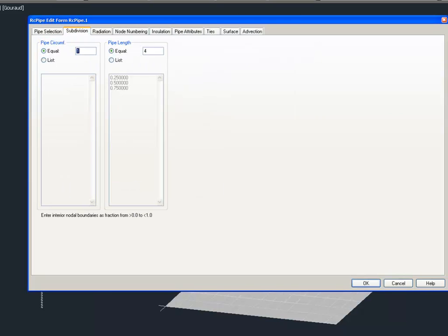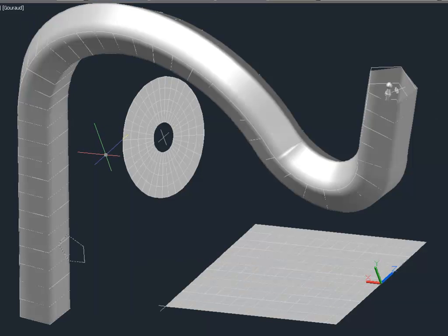And to make things a little bit more visible, I'm just going to put in about a cross-section of 40. Or excuse me, resolution of 40, and you'll see that it extruded along that warped center line. It extruded the pentagon, and that could have been a pipe carrying fluid, or it could have been a heat pipe. In this case, it's going to be a heat pipe.